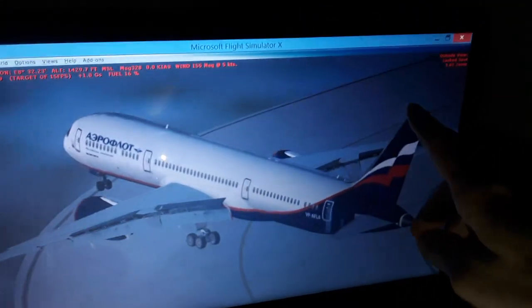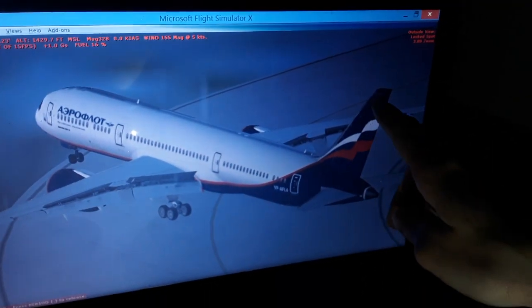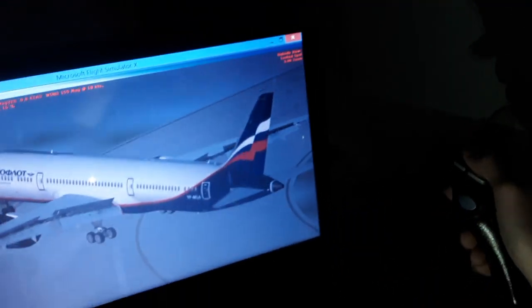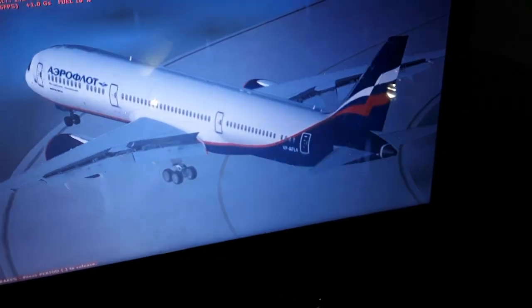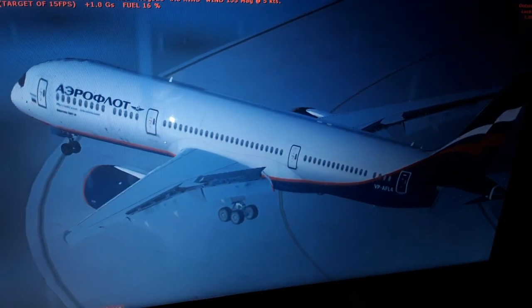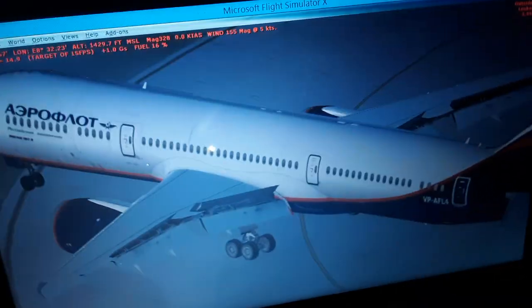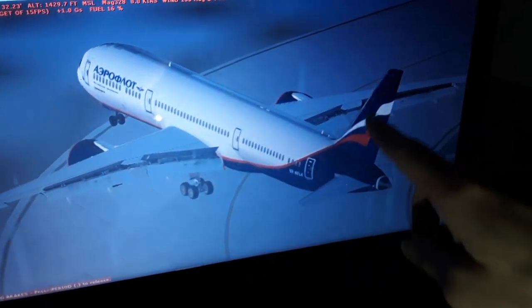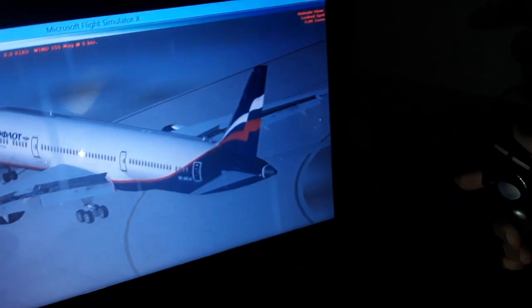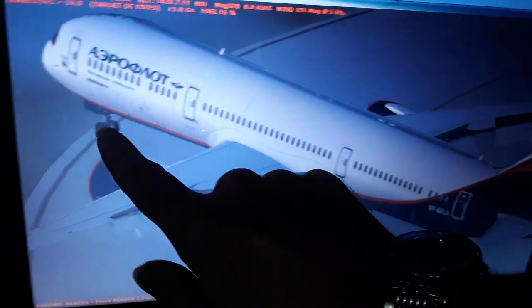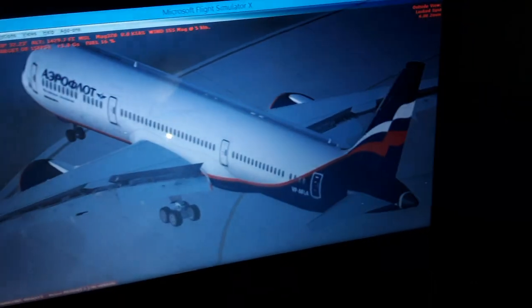Then as we accelerate faster above 45 knots or 72 kilometers an hour, the rudder becomes aerodynamically effective. So the computer will limit the forward nozzle from 76 degrees to 7.6 degrees left and right. Also, when we accelerate even faster above 80 knots or 144 kilometers an hour, the computer automatically will lock the forward nozzle to 0 deflection or small deflection like half or 1 degree.